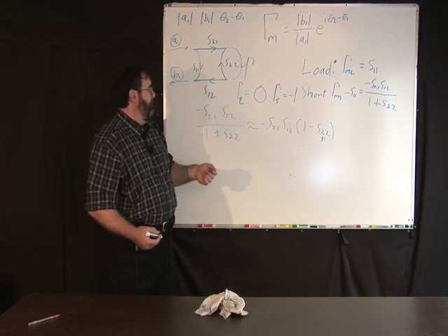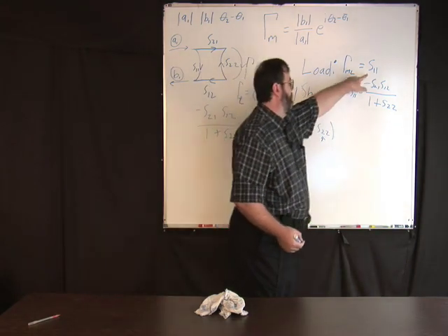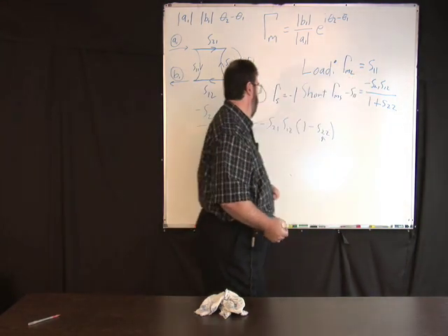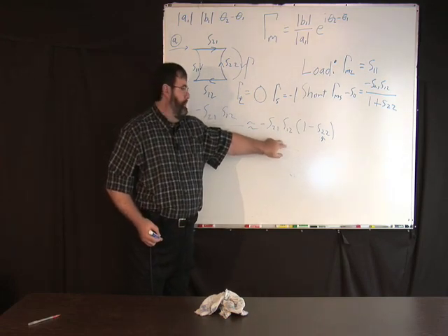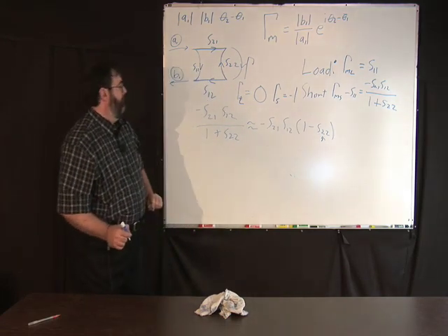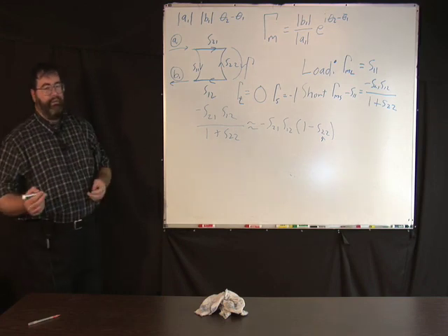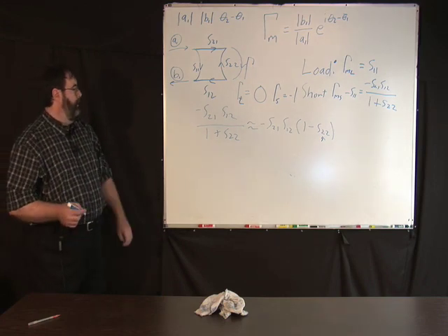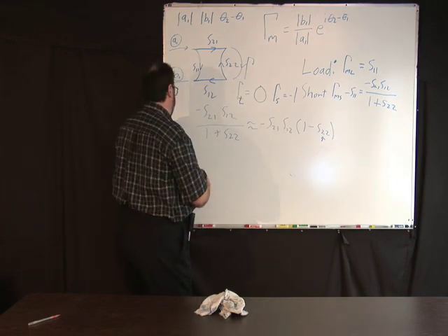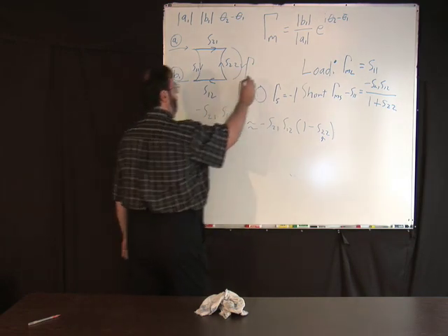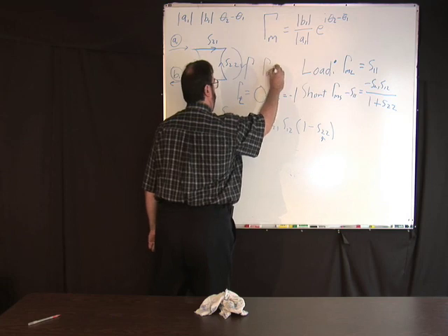So now from the load and short you know what the reflection is with no reflection in the reflectometer, and you know what the losses are, assuming this is small. But you don't actually have to assume it's small, because another thing you could do is put what's called an open on there. An open has gamma open equals 1.